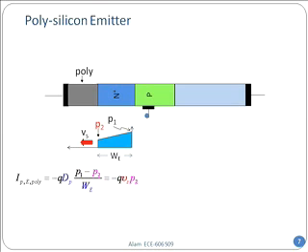So first of all, if you have a polysilicon emitter, I have I sub P because I'm talking about holes. I have an E in the subscript because I'm talking about holes going into the emitter, and poly because I am in the presence of poly. So those three things are there. Do you see minus Q D sub P, P1 minus P2 divided by WE?